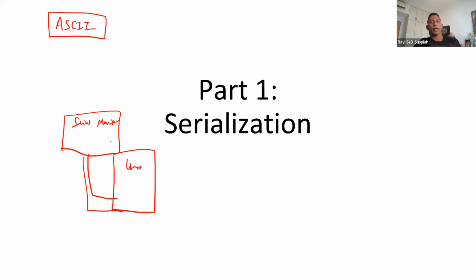So when I deal with an output device or input device that is expecting or generating ASCII codes, I need to be mindful of that. For example, in my Uno code, if I have a variable x and the answer is 1, I cannot send 1 directly over to the serial monitor.